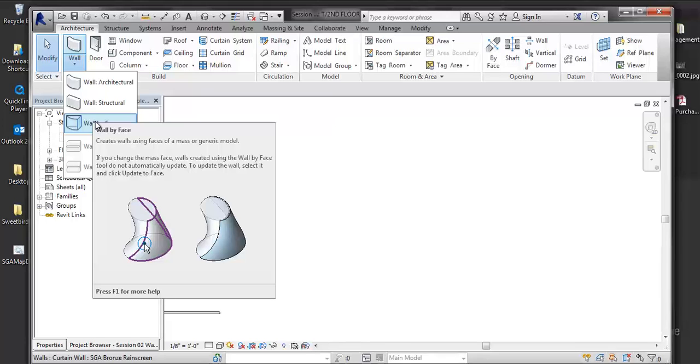The scope box was controlling the grid, so there's that hierarchy that one thing has to be hosted to another. The same goes for any system that's really not orthogonal, in this case, and has double curvature. So I can actually host a wall to a massing element that derives that form, and then I can really get to anything else we want. And we'll touch today on some really kind of double curved surfaces as we do imports and things like that.